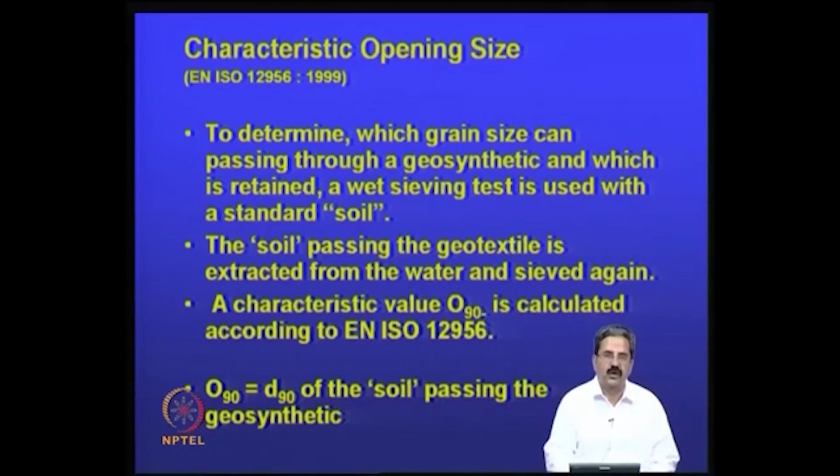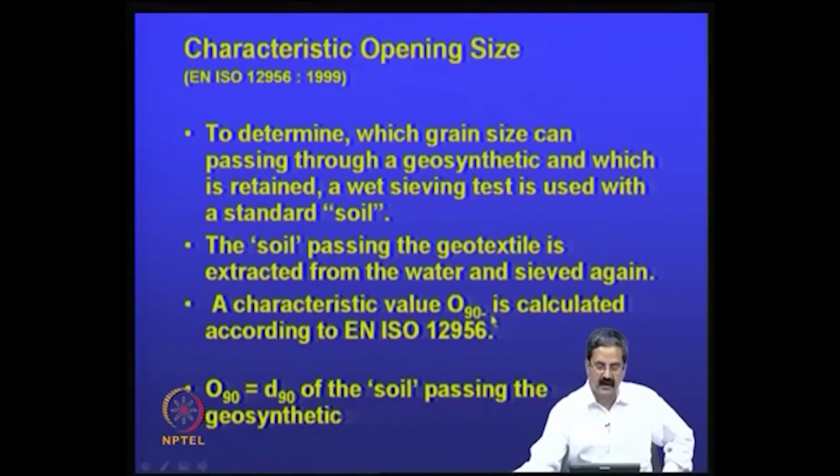Like see, we know we design the filters based on gradation size. We say D60 size, D10 size, D30 size and all that. Here we try to calculate what is the characteristic opening size, which is nothing but the size that 90% of the material can pass through.